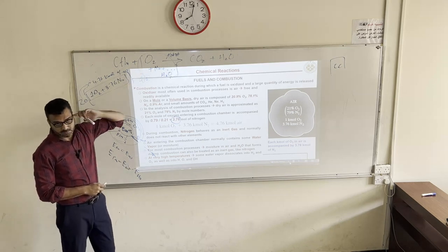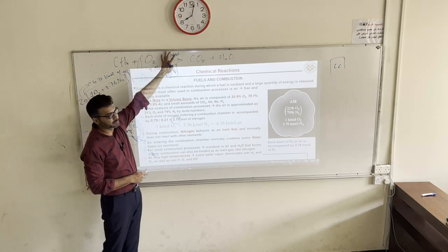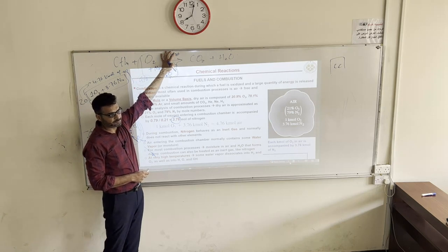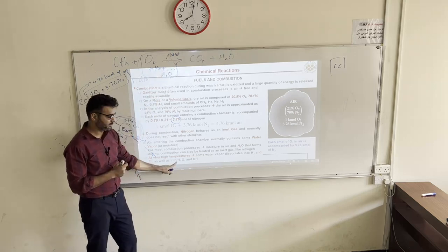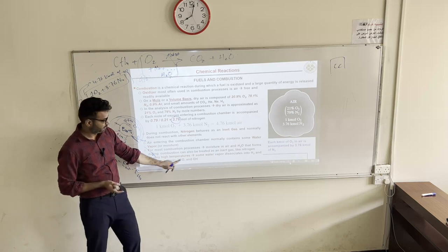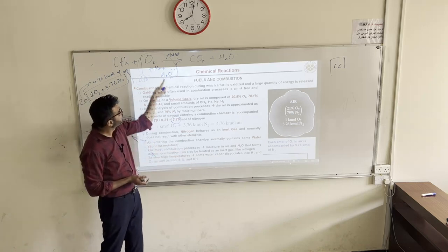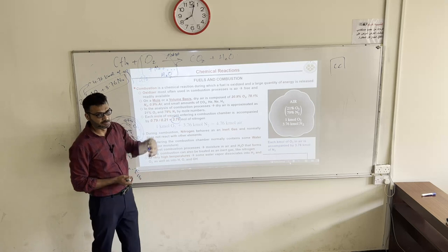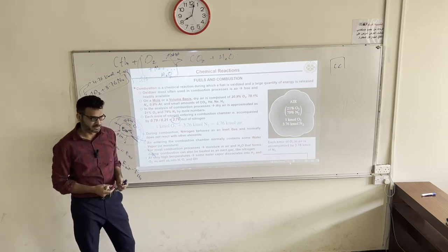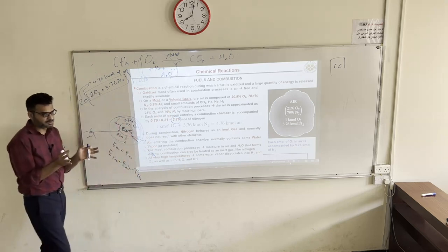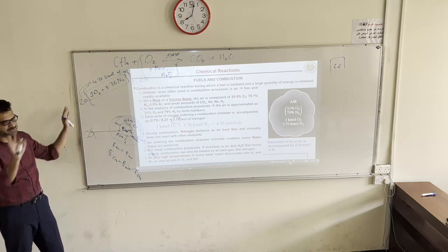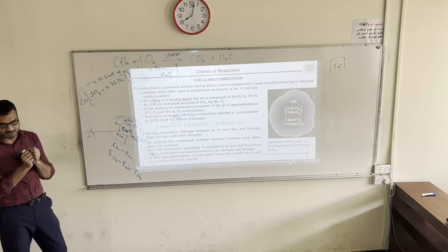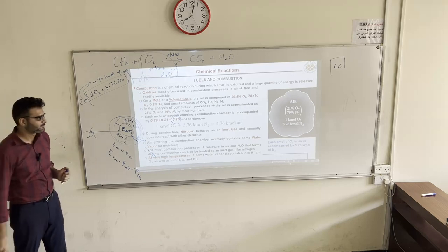During chemical reaction, of course, temperature increases to a very large value. If the temperature reaches a very high value, then there is a possibility that this H2O will dissociate into H and O or OH ions, or nitrogen may react with oxygen to produce nitric oxide, which are poisonous gases. We want to avoid those, but in actual combustion there are so many things happening. So here we'll see what is ideal combustion, which we want to achieve, and what is the actual one.